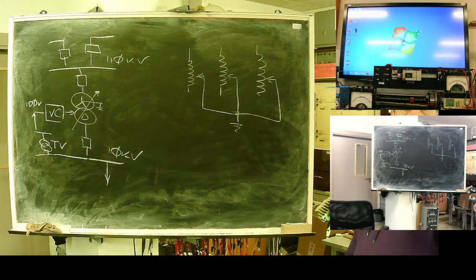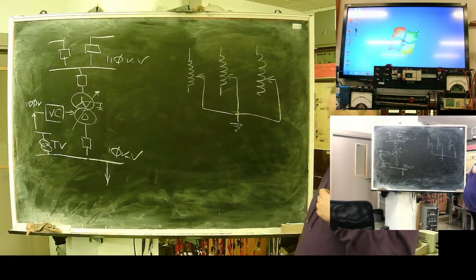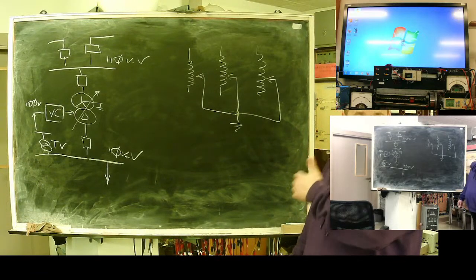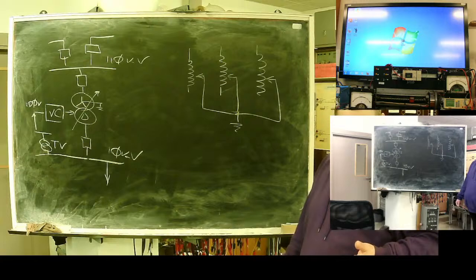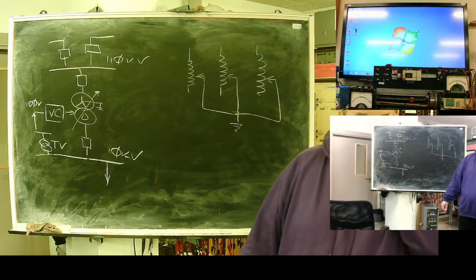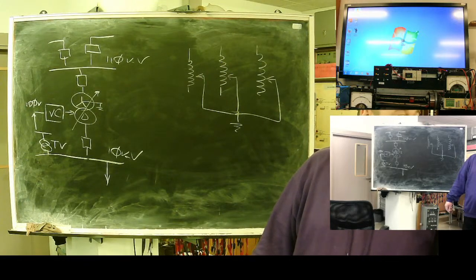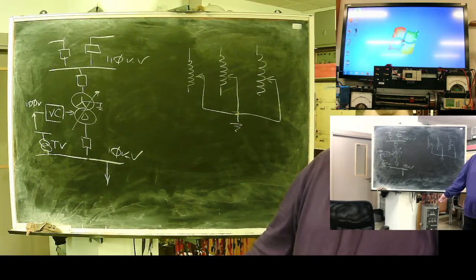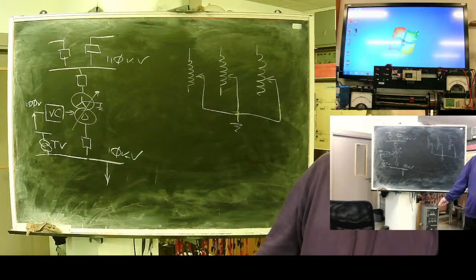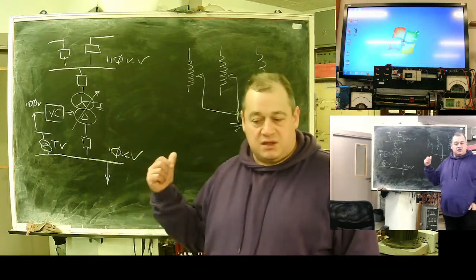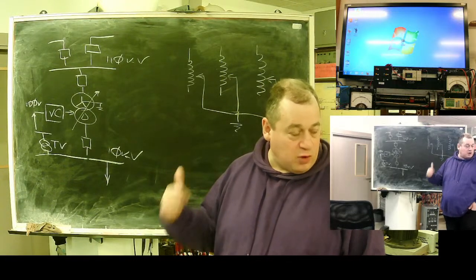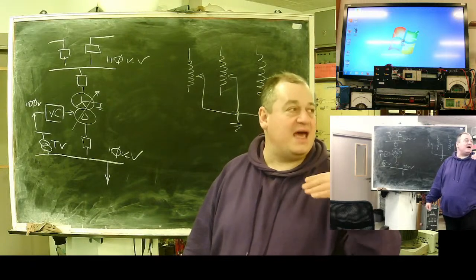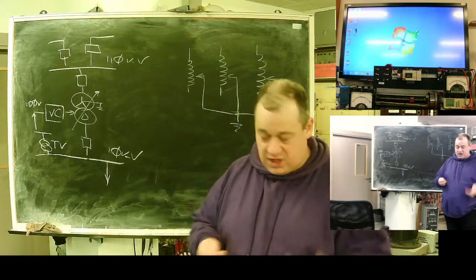So the load is variable. If voltage is left uncontrolled, unregulated, it will go down at the peak hour and rise above any reasonable level at night. So clients will complain, the public service regulator will fine the company. It's not a good idea. The voltage controller keeps voltage in the city network in an allowable range.